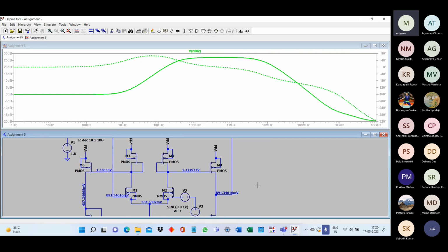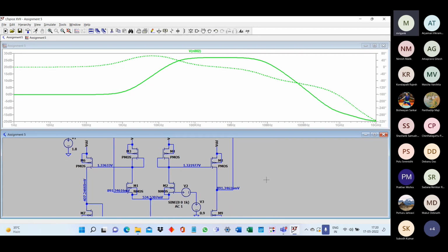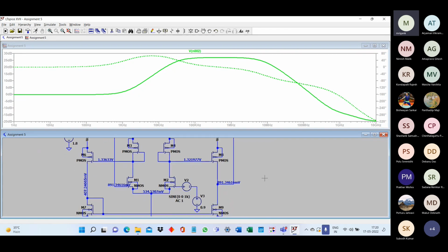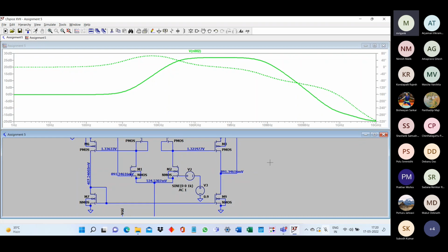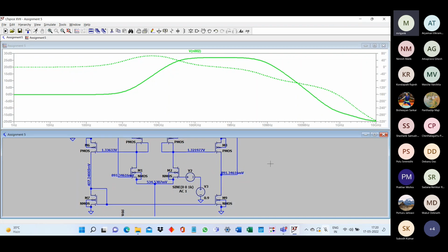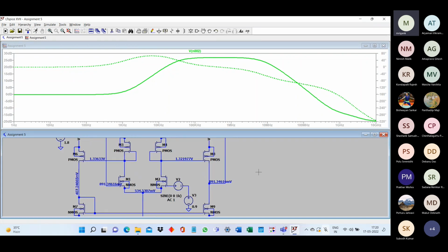The R basically is introducing a band pass response, because this R along with the parasitic capacitance of the MOSFET creates a band pass response. So apart from the low pass filter response that you get because of the MOSFET capacitance, this R and C of the MOSFETs, like if you just go to the circuit.